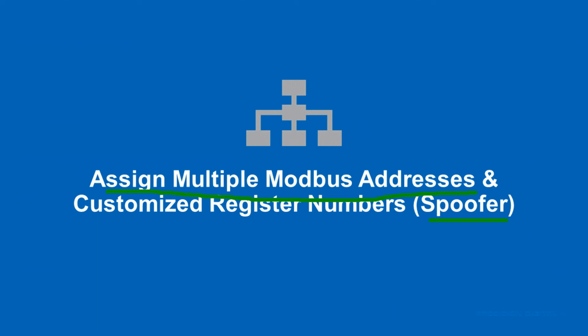but you can assign it multiple Modbus addresses so that it will respond not only when it's talking to the standard address you program into the Consolidator Plus, which is configurable, right? So you could, for example, set up your Consolidator Plus to be Modbus address 100. And so great, whenever anything talks to device 100, it knows it's talking to the Consolidator Plus. But you could also tell the Consolidator Plus, I want you to respond if someone talks to device 101, or device 102, or device 103, or device 12. Any addresses you want to tell it to respond to.